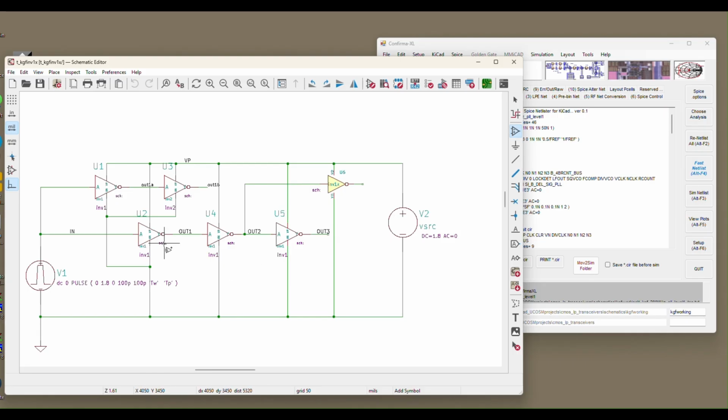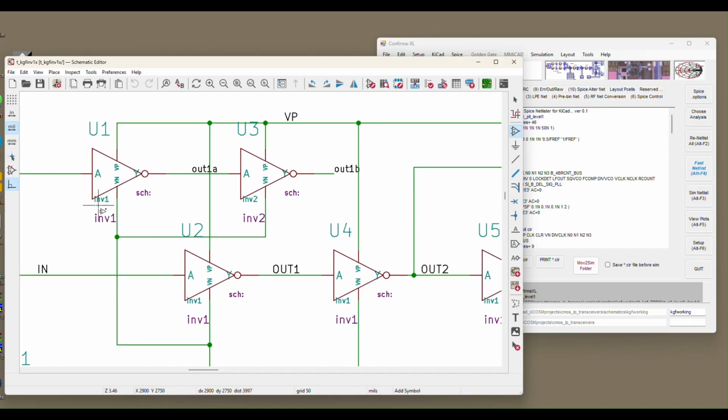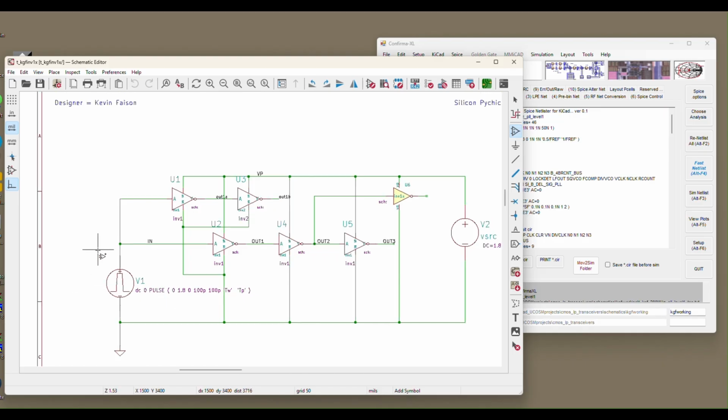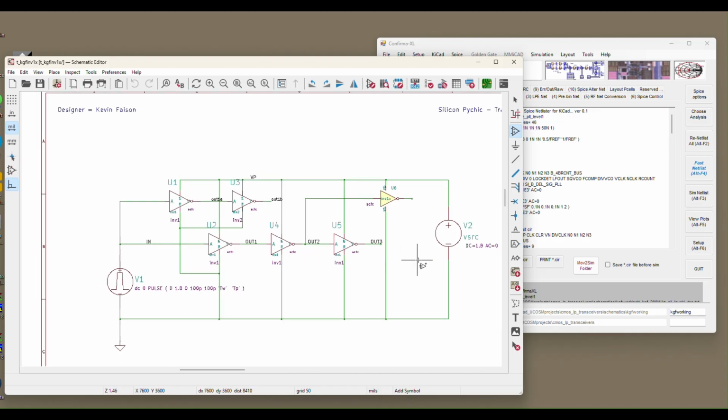So what we have here, we have just some simple inverter gates. There's two different sizes. I guess this one's what I would call a 1x inverter, and this one here is a 2x inverter, and they're just driven by a pulse train just to exercise those gates. And those gates, they're transistor level, and they're tied to a 1.8 volt supply. I think in this simulation it might be TSMC or Tower 0.18. I don't recall exactly.